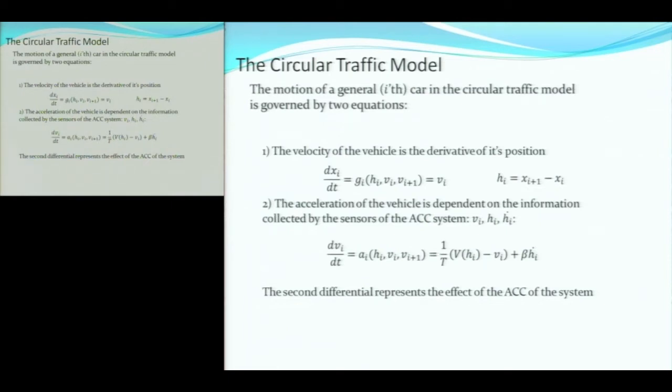From this equation, we can see that the acceleration of the vehicle would positively correlate with the increase in the relative velocity, because if we see that the car in front of us is traveling faster, we would tend to also travel faster. Also, the acceleration decreases with the velocity of our car because if we travel faster, we want to be more cautious and tend to slow down. Now, there's also a dependence on the headway, like I previously said, and this dependence is expressed by something called the optimal velocity function, or V of h, over here in the brackets.